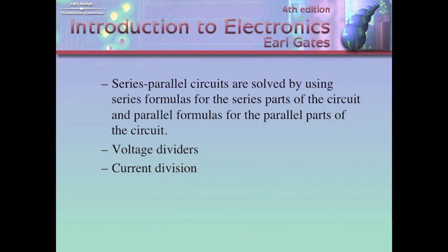Once we determine this, now we can calculate how much resistance is going to be required to give us this voltage drop. R is equal to E over I. So 5 divided by 2.05 gives us the amount of resistance of this resistor.